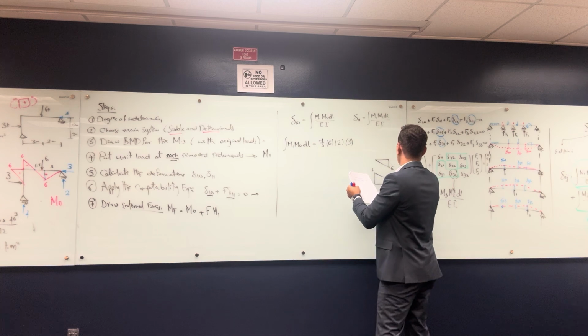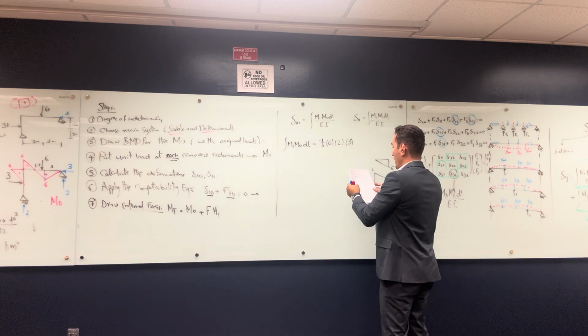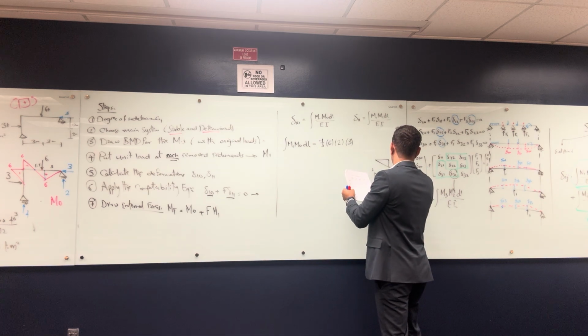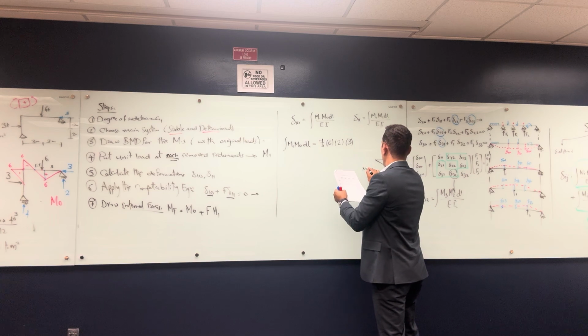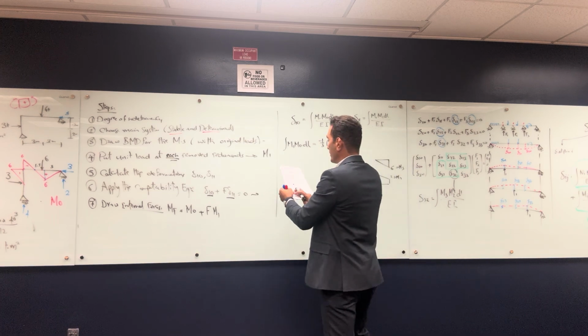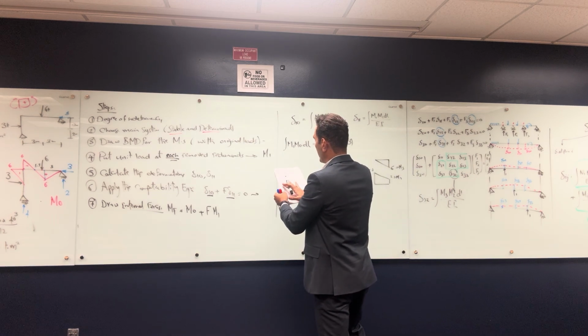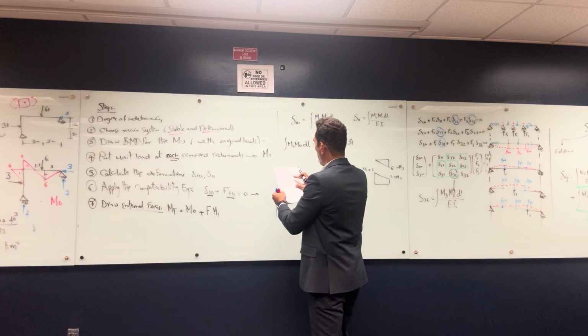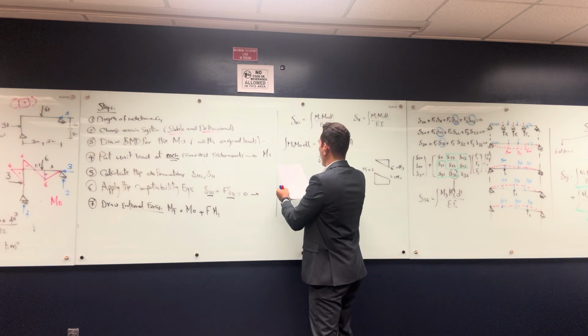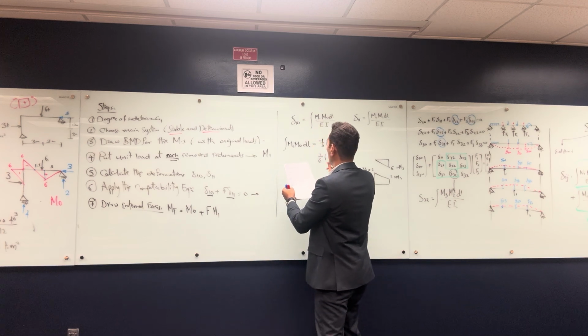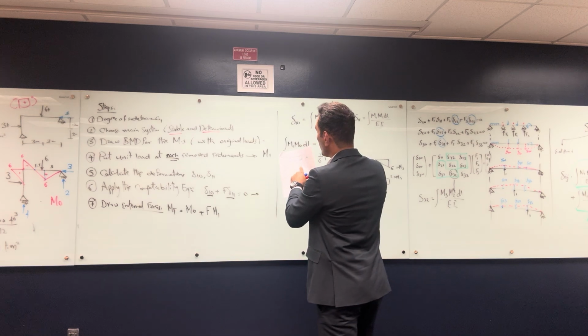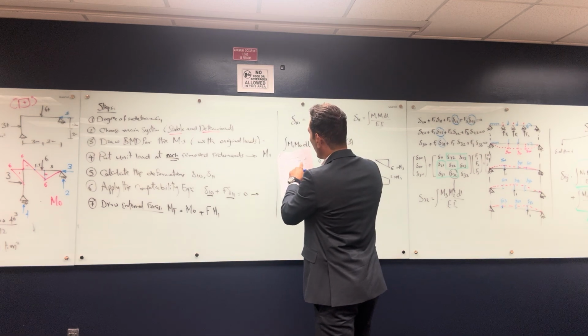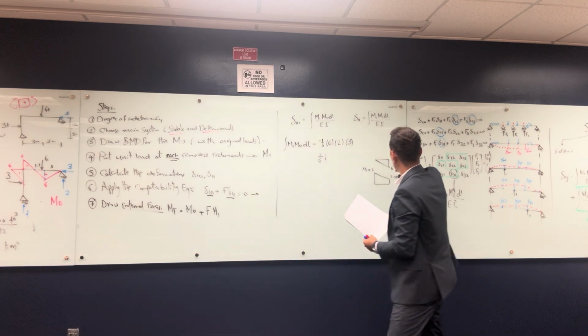This is M3, and this is M2, and this is M1. The tables are saying that if you have a rectangle with a trapezoid, it's gonna be 1/6 multiplied by M1 plus 2M2. But look, M1 plus 2M2, M2 is the one that is opposite to the number here.